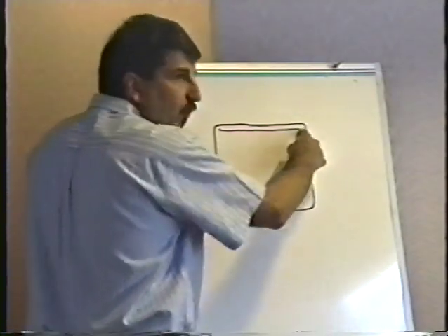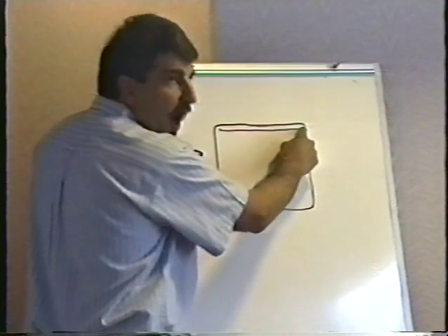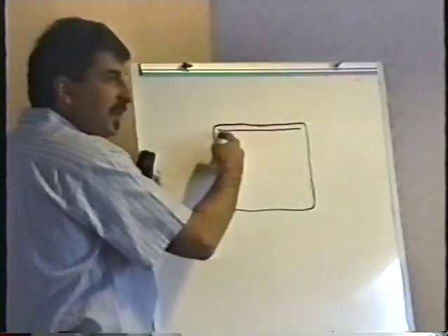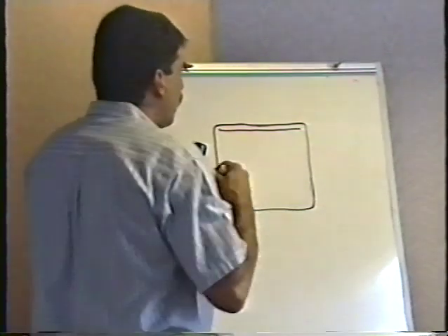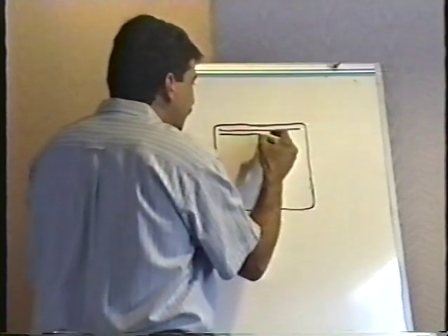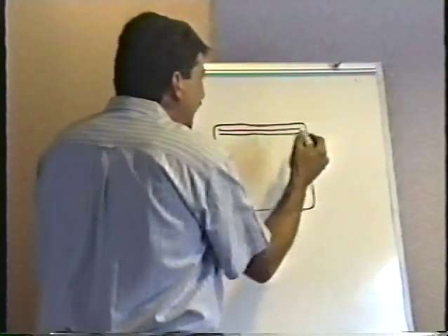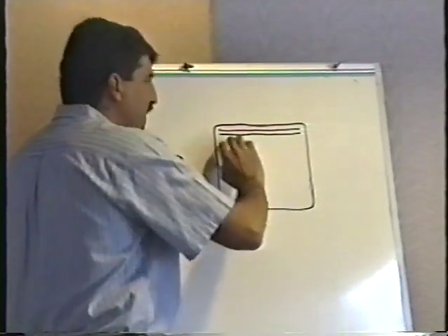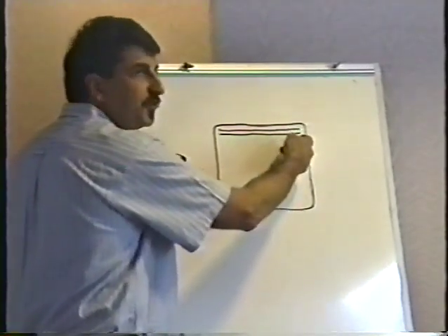When the beam gets to the right-hand edge, it is turned off. The magnetic field quickly resets to bring the beam back to the left, where it turns on again and draws another line underneath the previous line. It only draws the line from left to right. When the beams are at the right-hand edge, they're turned off.